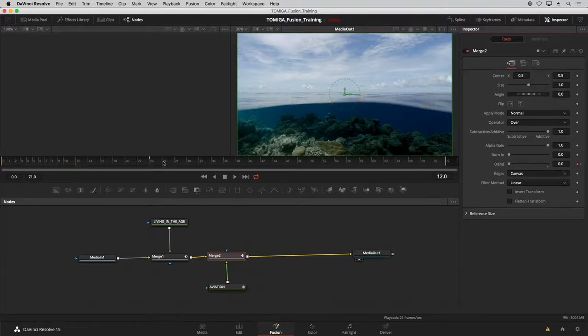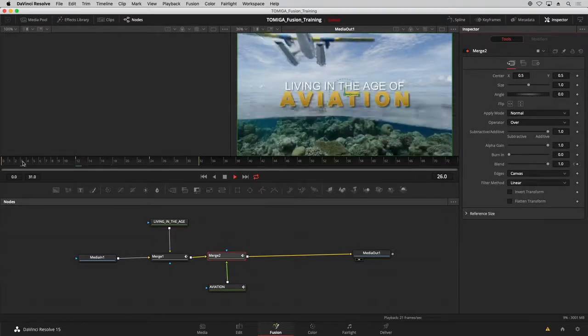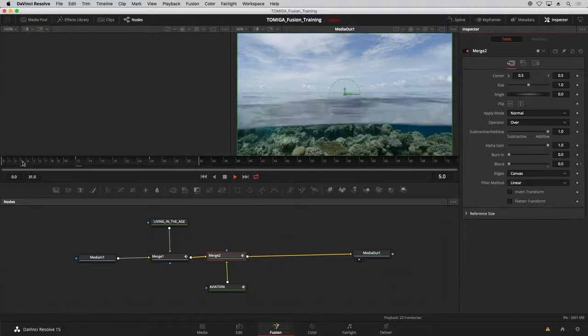So remember that render bar range we talked about earlier? Well, I don't want to play the whole clip. I just want to isolate the playback to just this area. So I'm going to hold my command key and I'm going to click inside the time ruler and just extend out. Just like that. I'm now just previewing my animation as needed as I'm working on it.